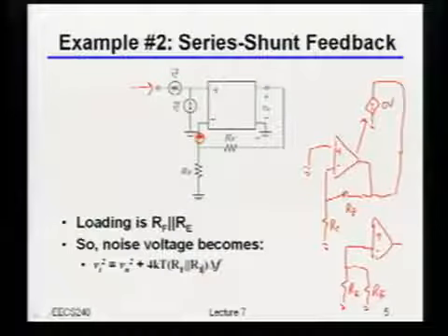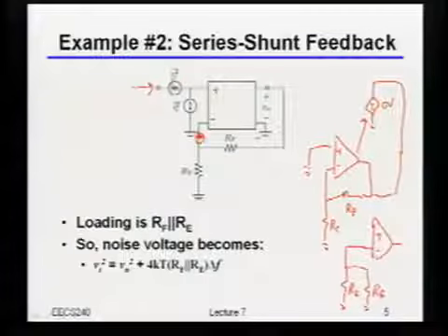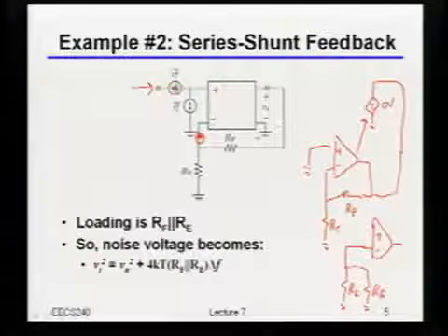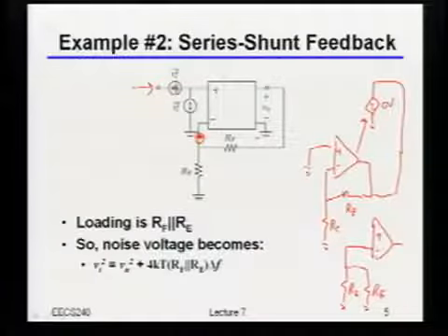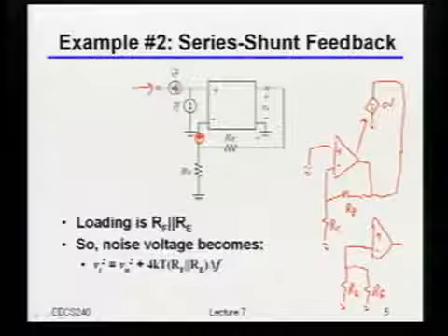So for something like this, just like before, I take that effective voltage noise and add it to the intrinsic voltage noise of my amplifier. Again, not that this is exactly correct, but 90-some percent of the time it gives you close enough to the right answer that, if I really had something complicated, this is basically what I would do to get a quick and dirty answer that's pretty close.